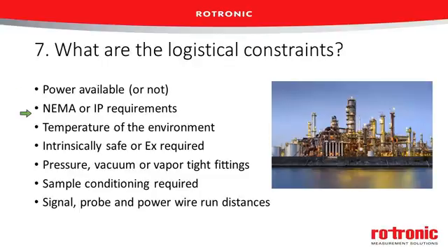It's good to look at if there are any requirements for NEMA or IP standards to be met by any transmitter. So think about whether the environment is going to see condensation on a regular basis, or is particularly dusty, or if possibly a clean room would be sprayed down. Do we need to be able to handle that type of environment and ensure that our electronics don't get damaged by something that's happening there?